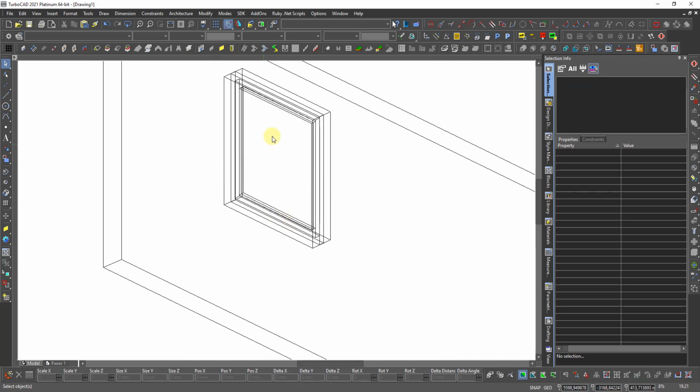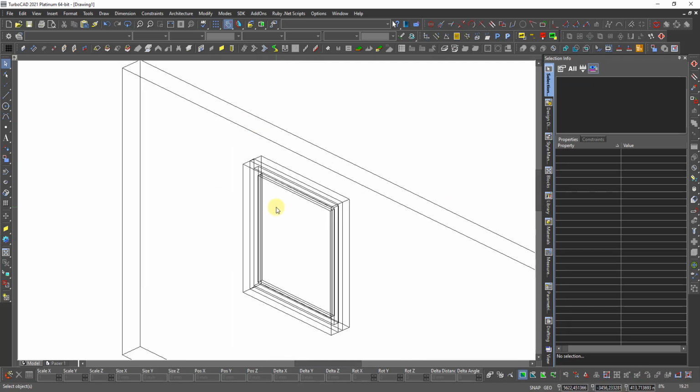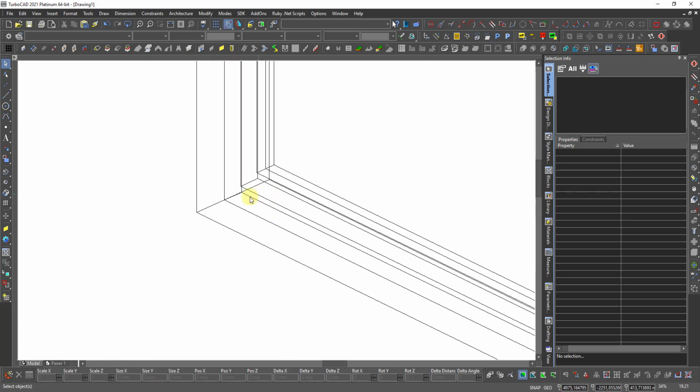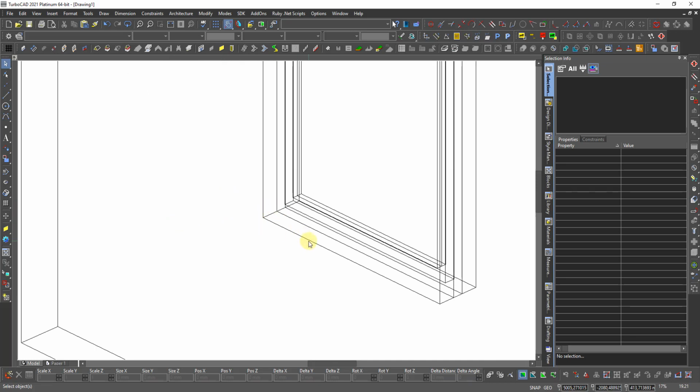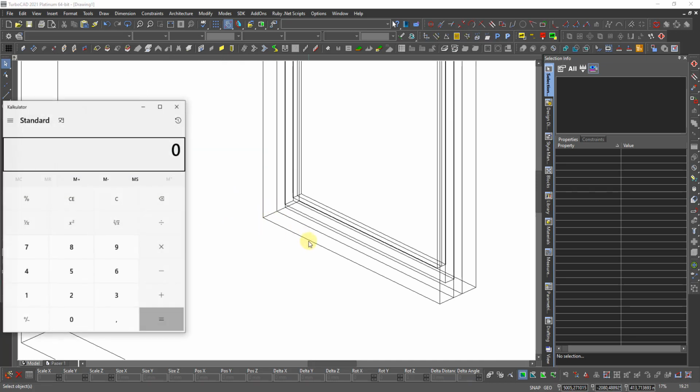Everything else in the measurement is the same, so it doesn't matter. I can also measure the inset value, but I can easily calculate it, because it's then always in the center. It's 215 minus 50 and divide by 2, which gives 82.5. That is the leftover.